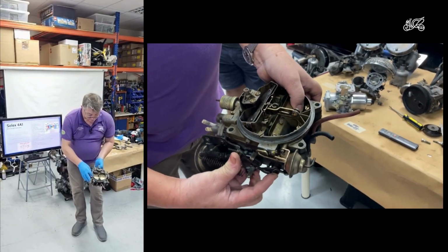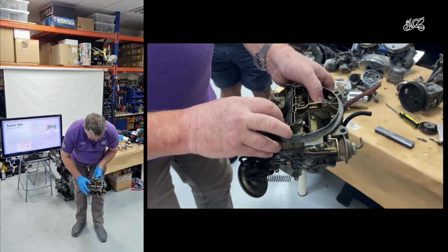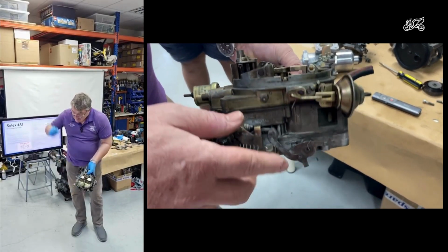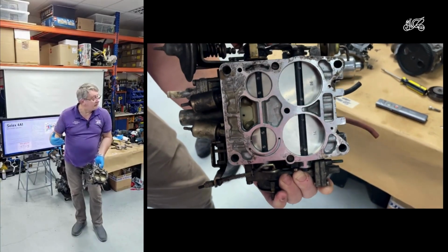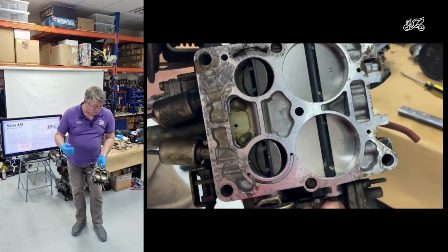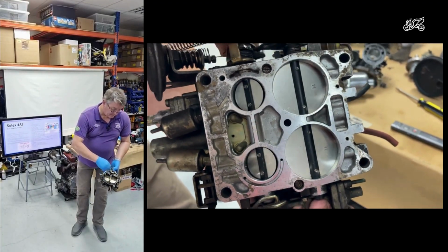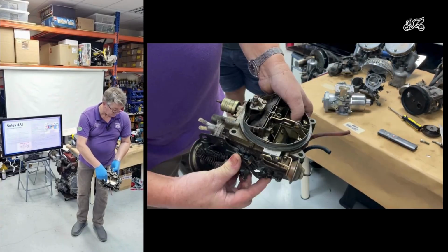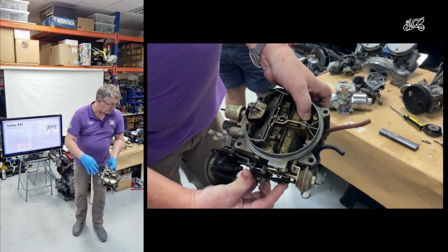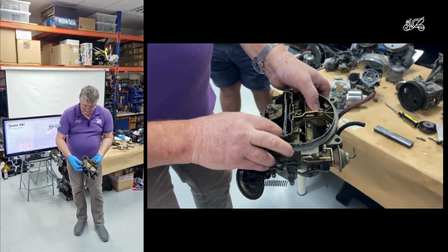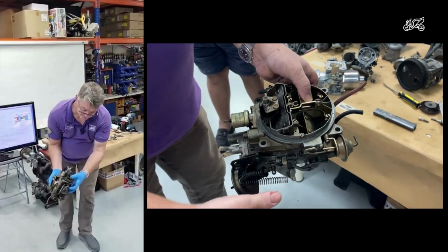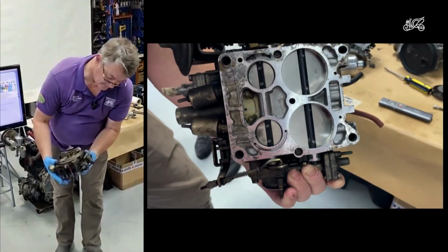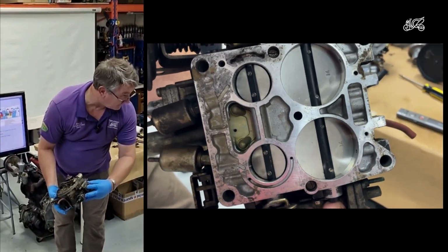But when you really put your foot down, this side opens up, and this is just a big hole with a big pipe in it. Yeah, so this adds loads of fuel so that the car will really, really perform at high speed. And it's got a slow running and a fast running section. The reason there's double is just for capacity in this particular case. And all of these, this is the accelerator pump, for instance, similar accelerator pump. This is the cold start.